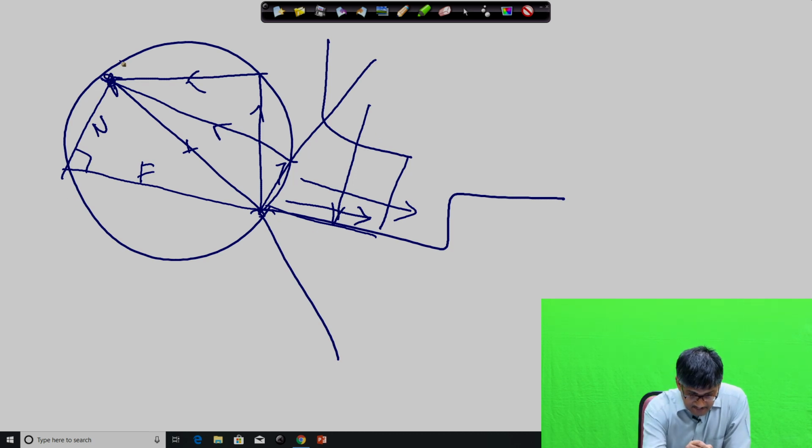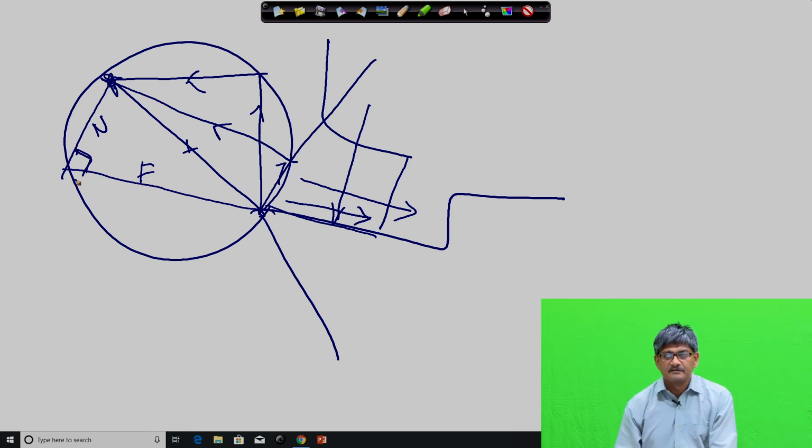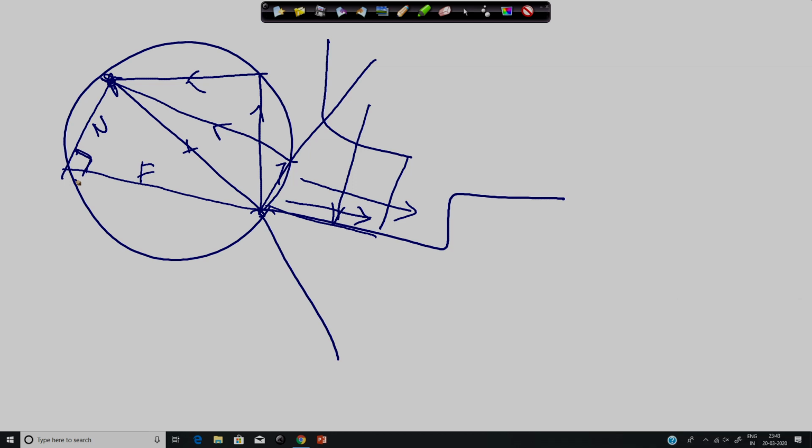So, if I represent the cutting forces in these two directions by resolving in these two directions, this ratio F by N gives me a sort of friction coefficient, and that is why it is referred to as apparent coefficient of friction. That is resolving the force in the direction of flow of chip and perpendicular to it, finding out their ratio, which we claim to be the apparent coefficient of friction.